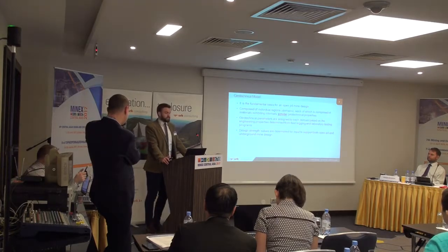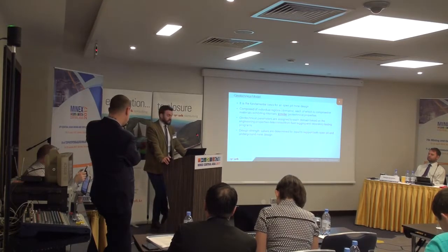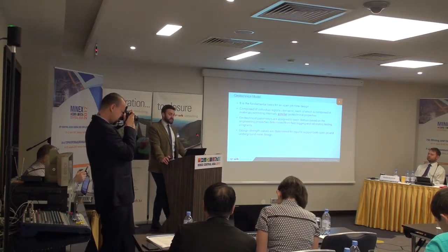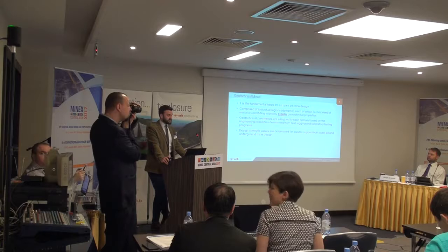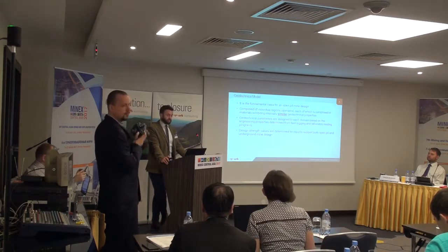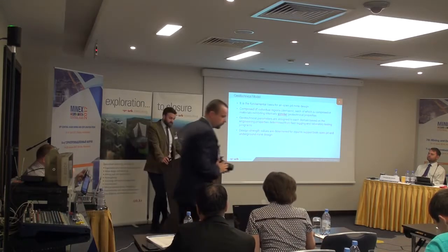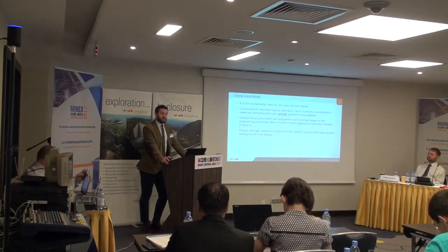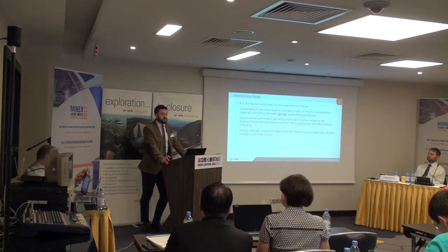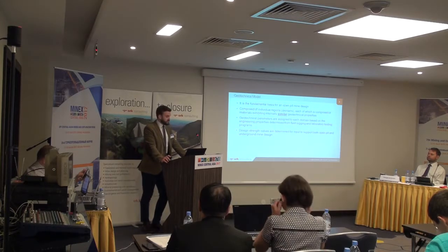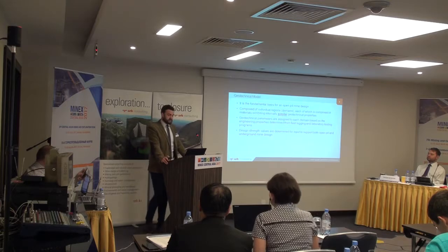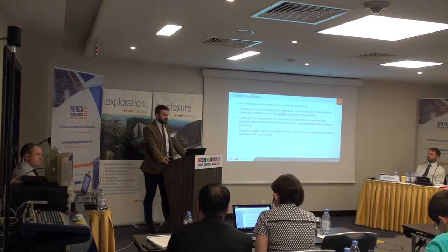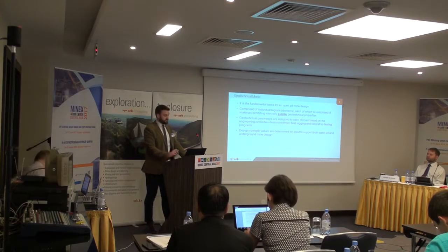So the geotechnical model is the fundamental basis for open pit mine design and underground mine design. It's composed of individual regions, each of which is comprised of materials exhibiting internally similar geotechnical properties. The parameters are assigned to each domain and should reflect the engineering properties of the rock mass based on your field logging and your laboratory testing. And the design strength values should be determined to input and support both the open pit and underground mine design.